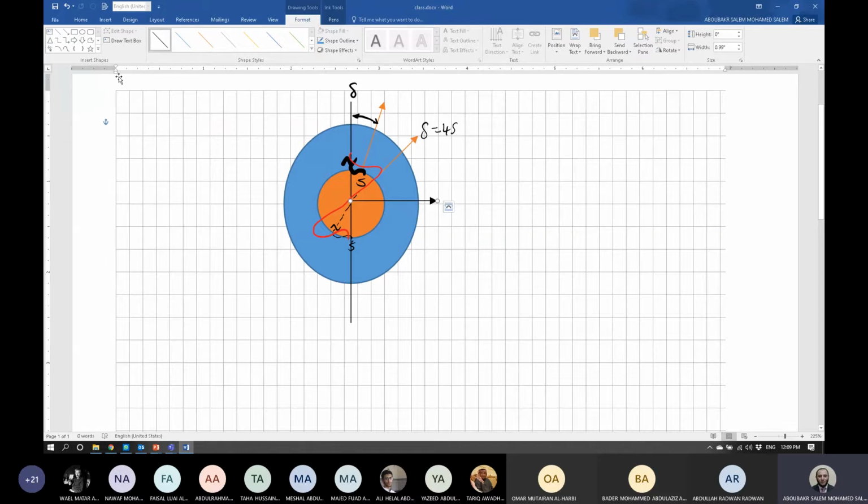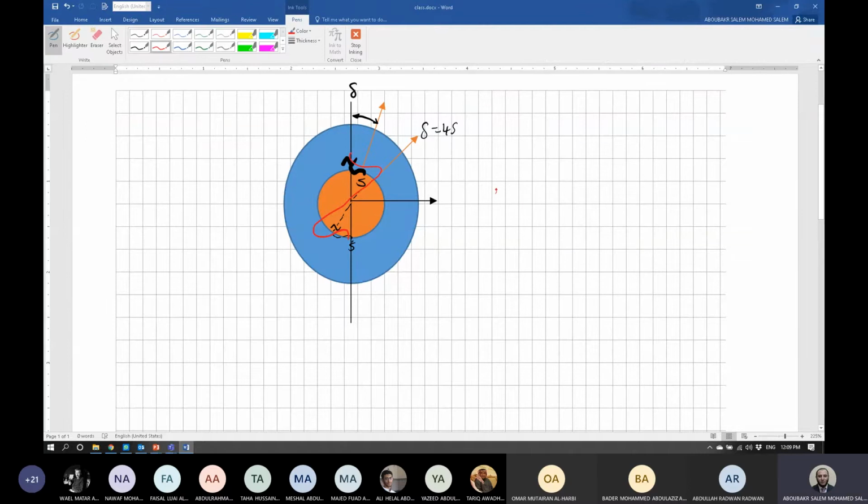So if delta equals 90 degrees, there will be something called machine loss of synchronism. Loss of synchronism means the flux lines do not exist anymore because of the big distance between stator and rotor poles, and in this case, guys, the machine cannot work or carry the load anymore. So this is, guys, the meaning of power angle now.